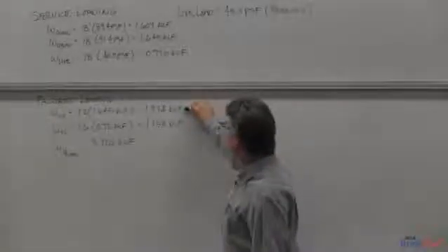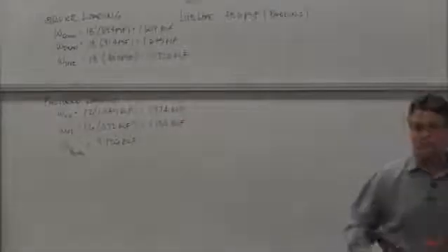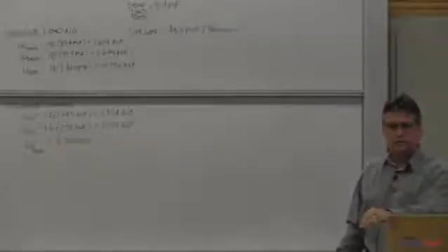Factored loading, 1.2 times the dead load, 1.6 times the live load. Add those up for a total. What am I going to use those for? Strength design. What kind of strength? Just flexural strength and shear strength. That's right.